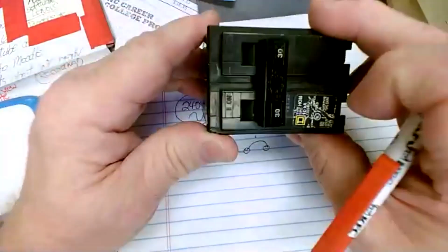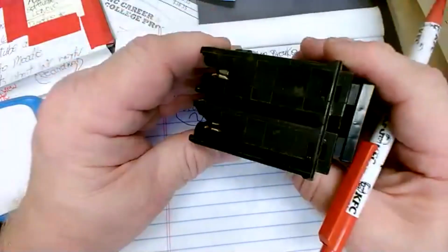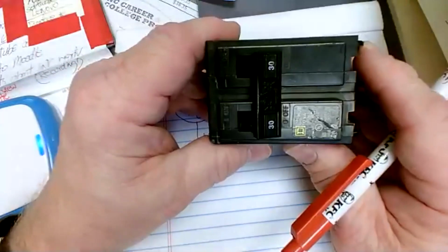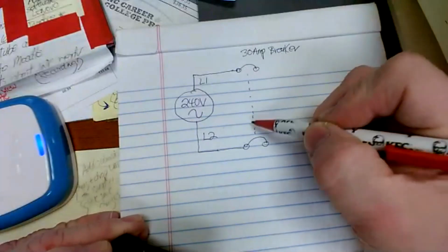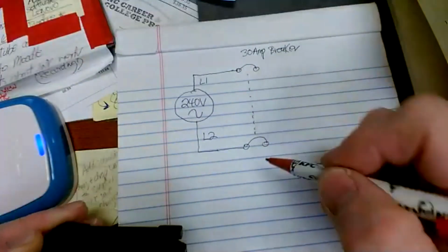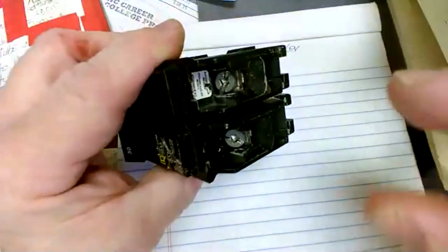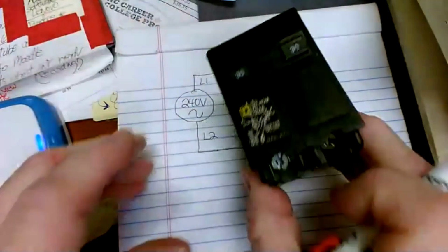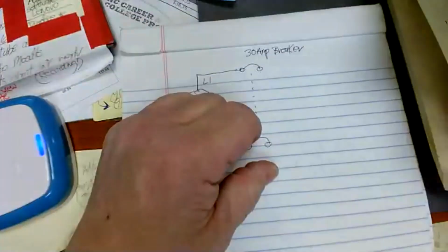Now, when this breaker goes in the panel, those of you that are taking residential, you know what this is already. You haven't wired the double pole yet, but you're going to pretty soon. These two clips here snap onto a bus bar in the breaker panel, and then the power runs through these symbols here that have a curve on them. That's a magnetic type breaker. Then you connect your wires to these lugs right here, and when you leave here, this is the panel, then it would go to your water heater circuit. So that's a typical double pole breaker. And a 30 amp is what you're going to be using most of the time on a water heater.